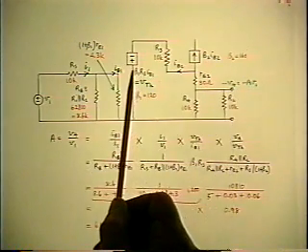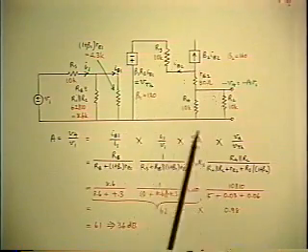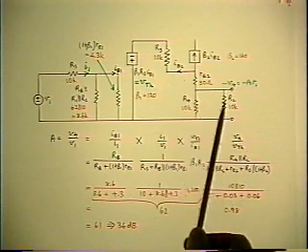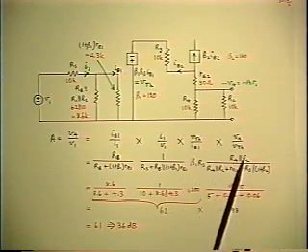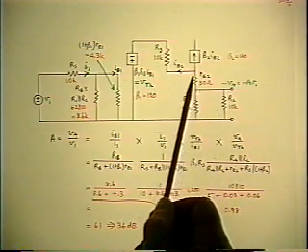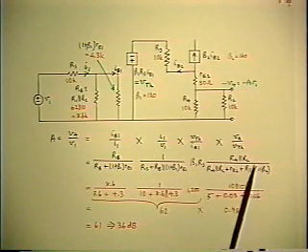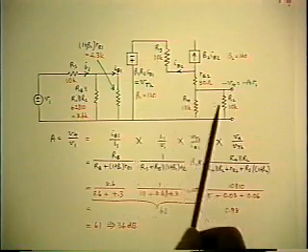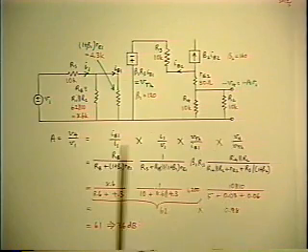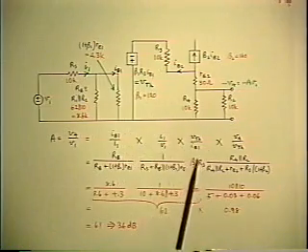V4 over V Thevenin is found simply from this rather more complicated voltage divider, which is the bottom branch, R4 parallel RL, divided by the same thing plus the top branch, which is RE2 plus the reflected R3. So the last fraction represents the voltage divider V Thevenin to V4. The factor in front is V Thevenin in terms of IB1, which is simply the value of that generator.